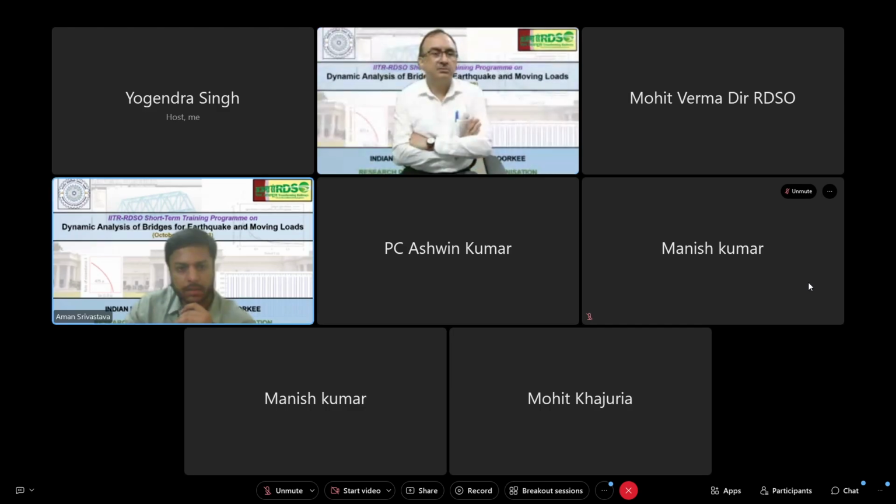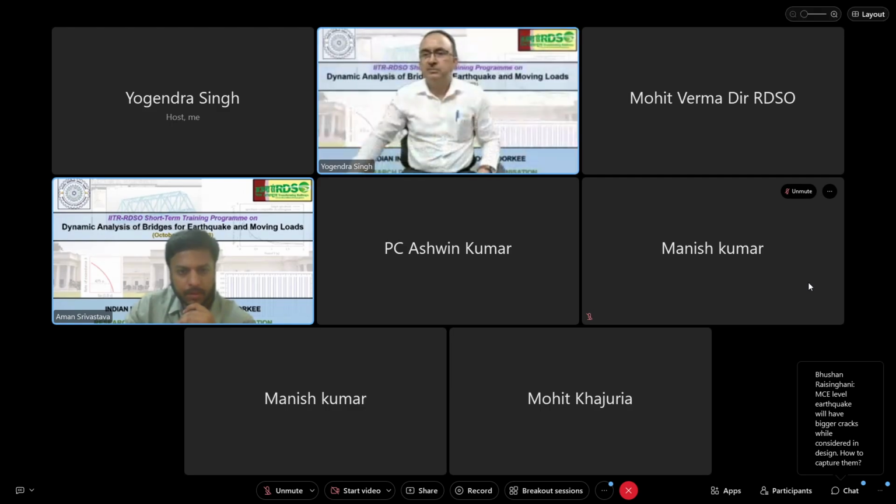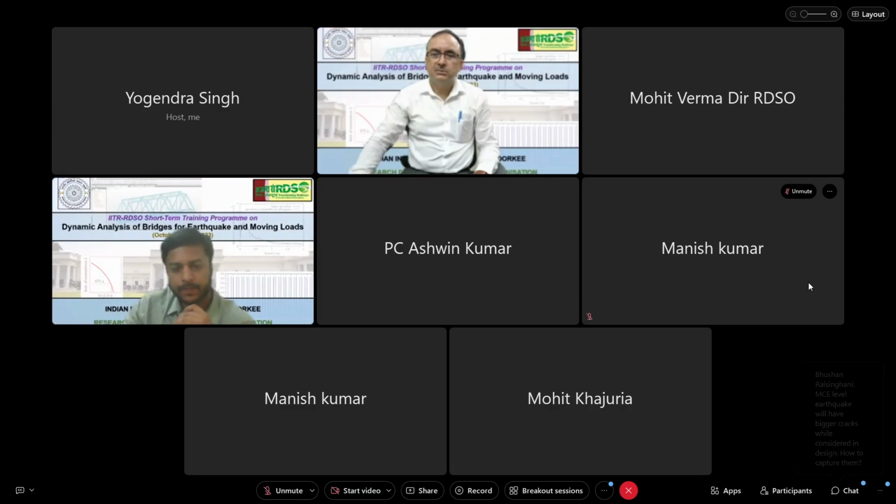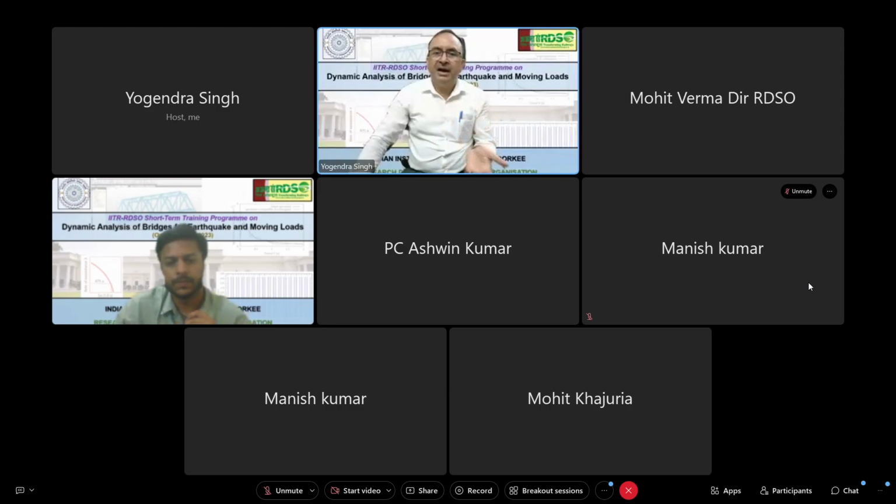Then we have a question from Mr. Jay only. What is the difference between equivalent linear response spectrum method and ERSM? ERSM is conducted for elastic structure. Equivalent LRSM is done for nonlinear structure, but by iteratively performing a number of elastic analyses.